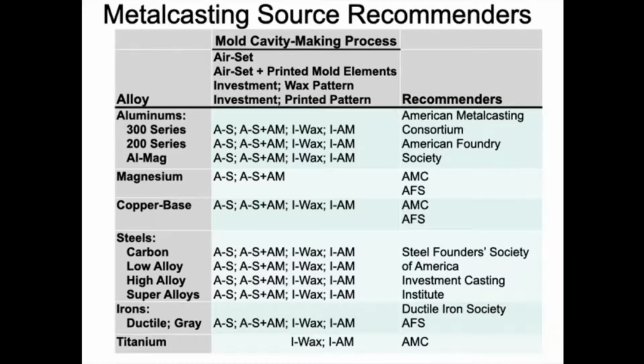For example, if I'm going to make a high alloy investment cast part, but investment wax tooling is not locatable, for typical small quantity DLA orders, I would want to select a mold cavity tool builder that will use investment tooling that was manufactured by an additive manufacturing method. The Investment Casting Institute will be a good recommender.